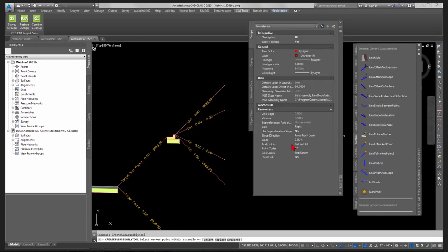And if I'm in a small fill, you know what? I'm going to come in and put in a 3-to-1 or 33%. Oops, 33%. Don't put in 0.33. Tab. And I want to put that right there.